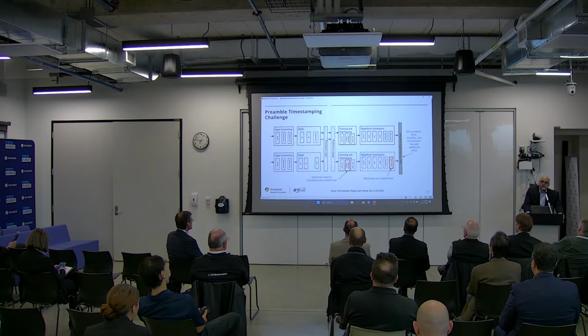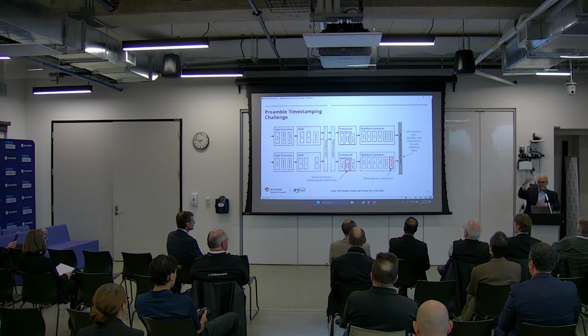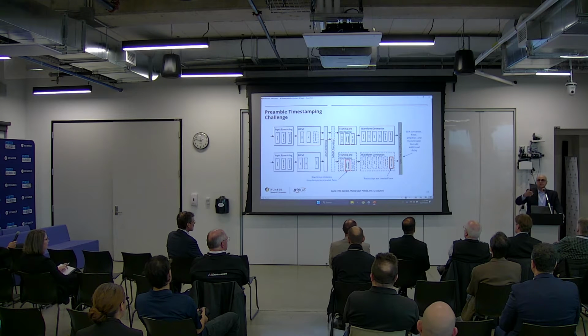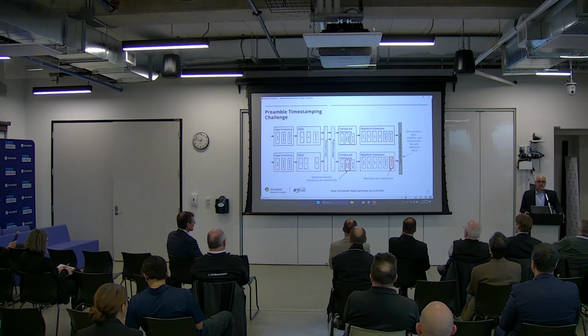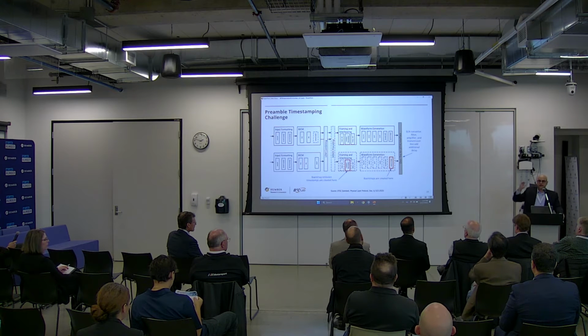Now, this is the transmit chain. When you have a frame structure, it's really nice: bootstrap comes first, then the preamble that has a timestamp. But when they're created in the transmit chain, it is not in that sequence. The timestamp is created somewhere in the middle of the chain, and the real waveform is created sometime later, the second block you see. Then the signal goes, still in the digital domain, and then you have to convert digital to analog, and then it goes to the analog equipment, amplifiers and the transmission line. And the transmission line is huge.